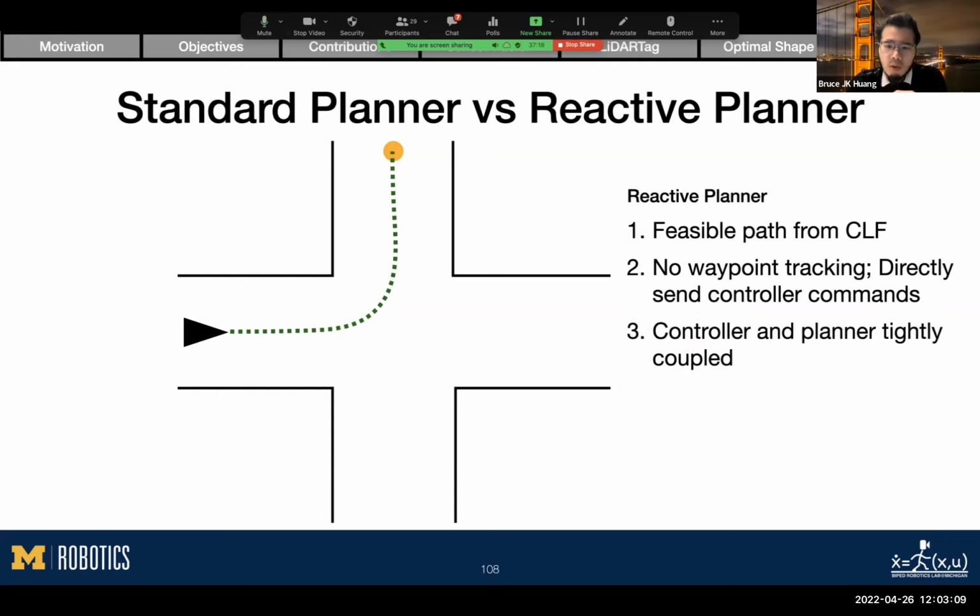Therefore, the low-level controller running on Cassie is tightly coupled with the planner. The benefit of it is that we can send terrain properties such as friction, type of terrain, or slope to the controller if needed. This would help us tackle undulating terrains, staircases, or even unstructured steps.